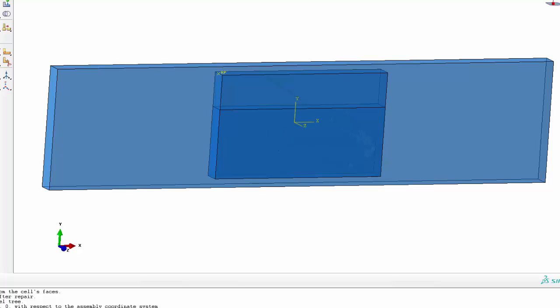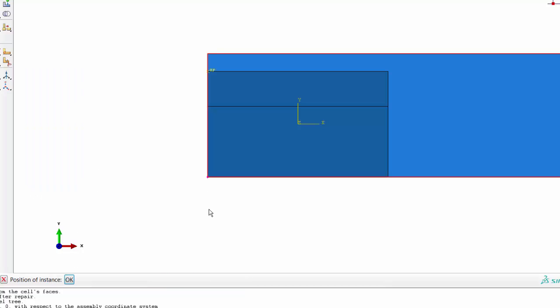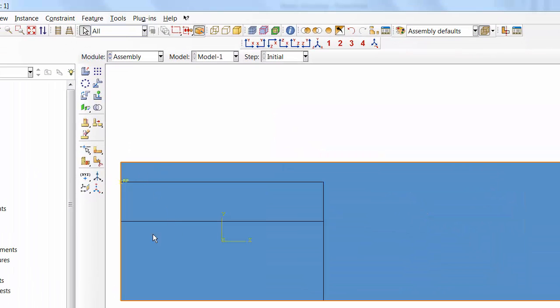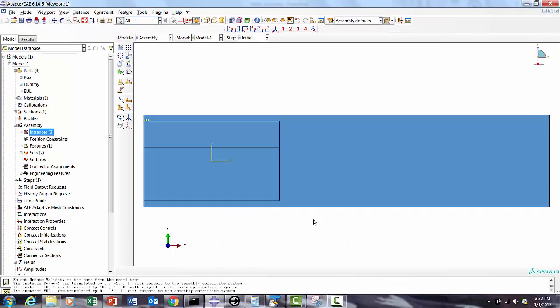And the other thing we'll do is position the Eulerian part from this to this, so they are aligned. The only thing is we'll take this down and then a little bit back. So I'm going to translate this 0, minus 5, 0, so they come to the center, and then I'm going to take the Eulerian mesh back 5, 0, 0.